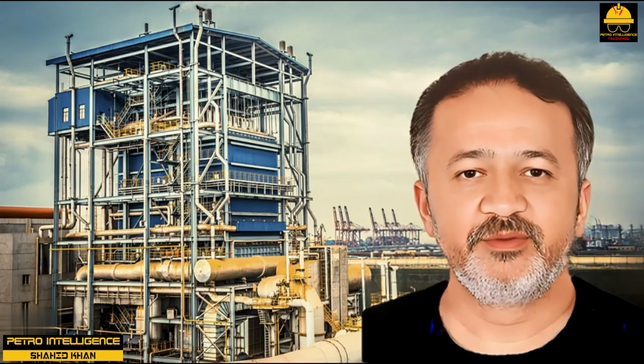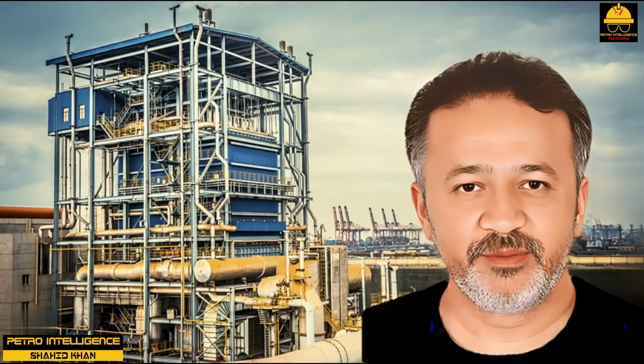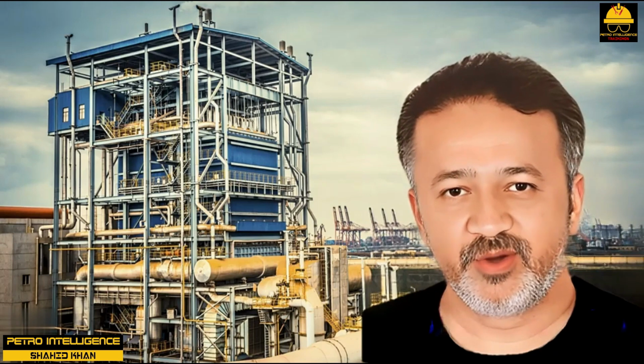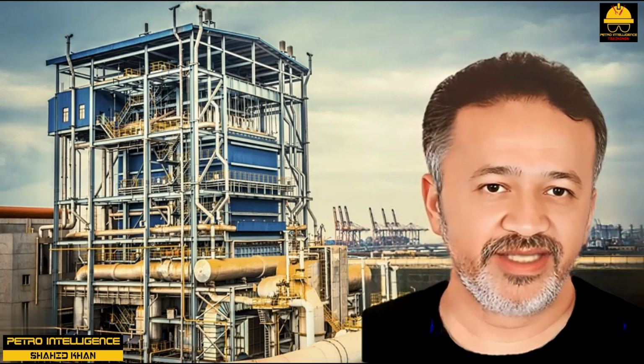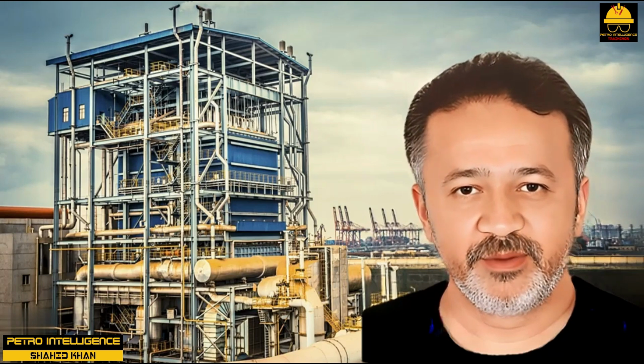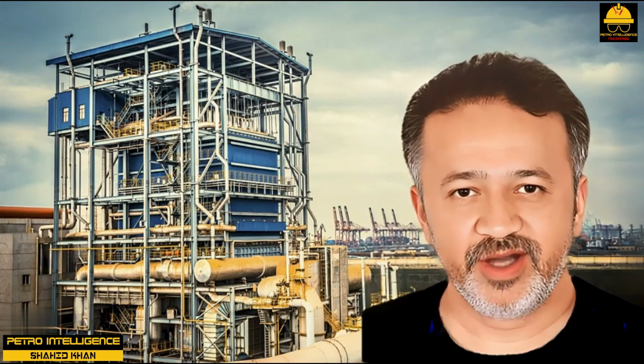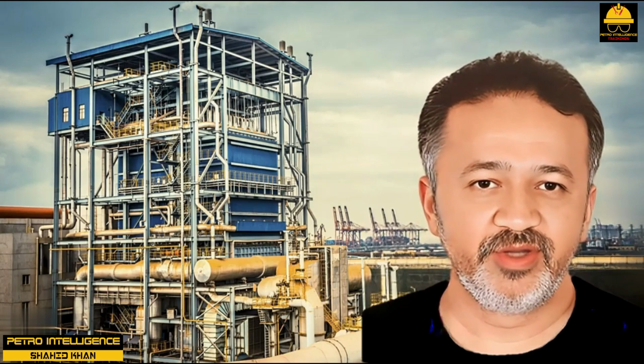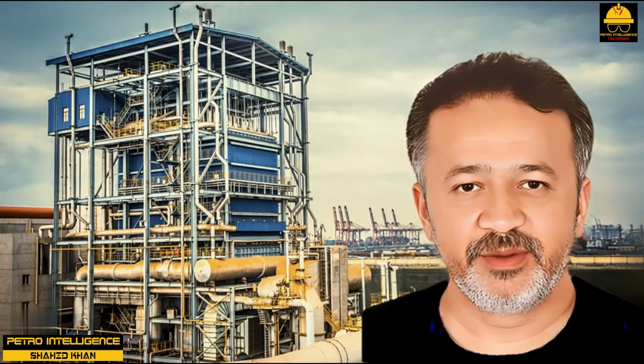It is clearly most important to carefully evaluate the suitability of the service that you intend to retrofit, consult and work closely with manufacturers of the equipment, ask around and seek out other similar applications to compare performance of the retrofit in the field. You cannot fight heavy fouling service with these inserts. The metallurgy of coil and corrosivity of fluid must also be considered.